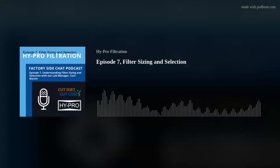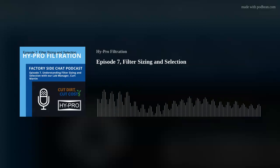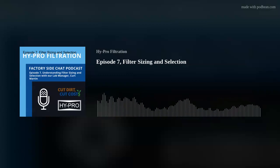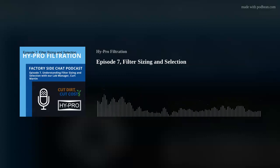That's really good information. And one other aspect I'd like to add to that is higher flow rate is not always better. Let's pick on a tank that's 500 gallons or a tote that's 330 gallons, and pick two flow rates, 5 gallons per minute or 10 gallons per minute. A lot of people would say, well, let's just go 10 gallons per minute. Well, it'll work. But if you have time and the ingression rate is not really high for the system, with 5 gallons per minute for the same size filters used on the cart, you're going to be able to pack in a lot more dirt in that filter element.